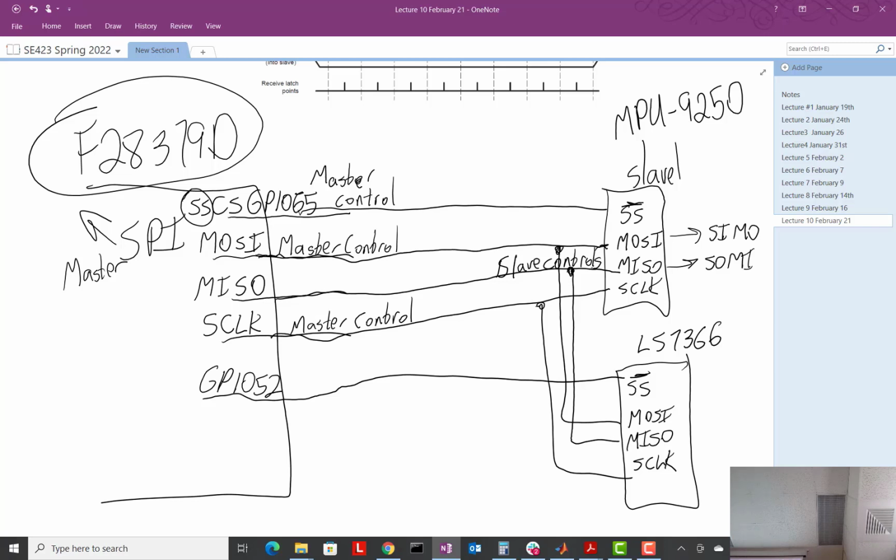So you'll see in my code, in your code, there may be times we send over data and we have to read it in, but we'll just put it into a temp variable and never use it. Because we have to read it to get it off the buffer, okay? But we can just not use it. So I'll call that a lot of times garbage data. Okay? Things that we just have to read off just so that we can read off the good data.